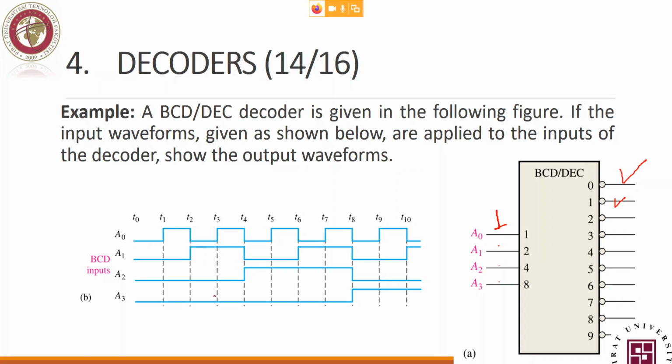Go to next. 0, 0, 1, 0. Well, okay. 0, 0, 1, 0. So we have 1 here. And we have 0 here. What will happen? So we have 0, 0, 0, 0. So 2 will be activated. The input 2 will be activated here too. Alright? Why? Because the rest are zeros. 2 will be activated. So 2 will be low, active low. The rest will be all high. Take another number with two 1s: 0, 0, 1, 1. Okay? 0, 0, 1, 1. So we have 1 at 2.